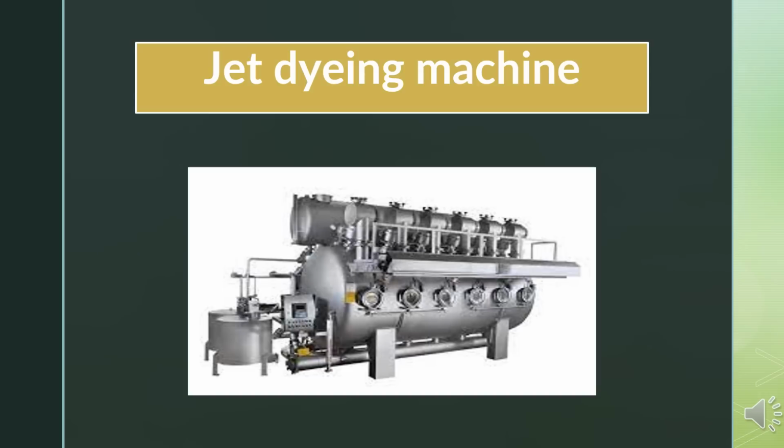1. Jet dyeing machine. Here the two ends of a fabric are stitched together, thus forming a huge roll or chain-like continuity. The fabric in this form is then put inside a closed chamber through which water with dyes and chemicals dissolved moves fast in the form of jets. The pressure of the jet makes the fabric move slowly inside the chamber, helping to achieve uniformity. Since the fabric is not under much tension, this kind of dyeing machine suits almost all kinds of fabrics.